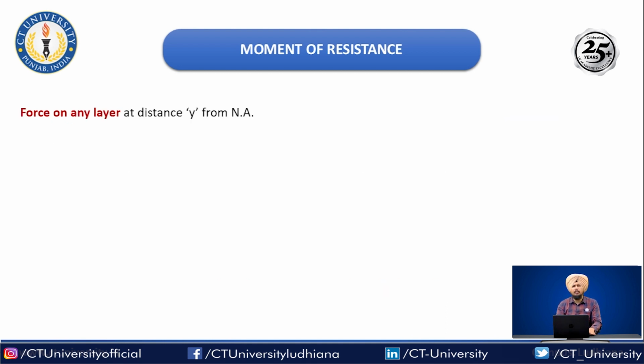So mathematically we are finding the expression. First we will calculate the force on any layer. We are talking about any layer having a distance y. But how can we find the force? Again, the stress is force upon area. From this value we can calculate the force in any layer. So the force will be equal to stress multiplied by area.